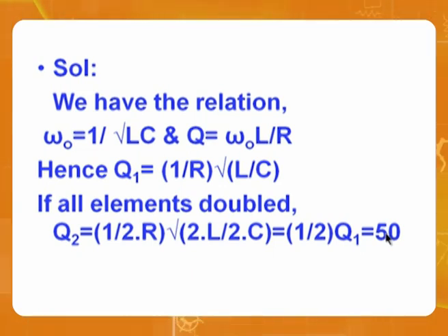It's a very simple equation. So be aware of these equations. The equation is omega naught is 1 by root LC. Bandwidth is R by L. And bandwidth is equal to F0 by Q. So Q is equal to F0 by bandwidth. So this is how we can get this bandwidth equation and convert this into here. So this is how you can get the answer as B.